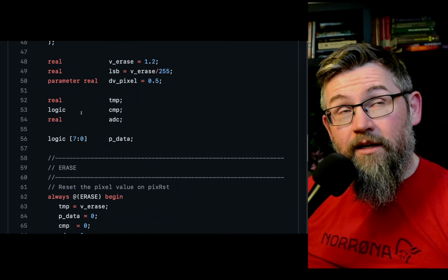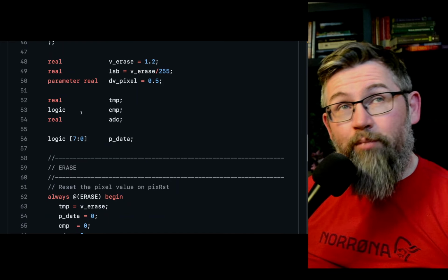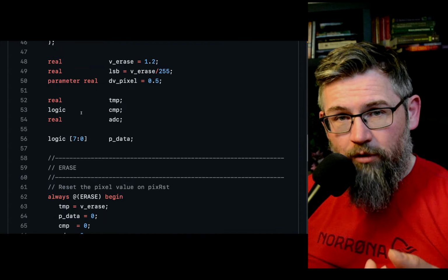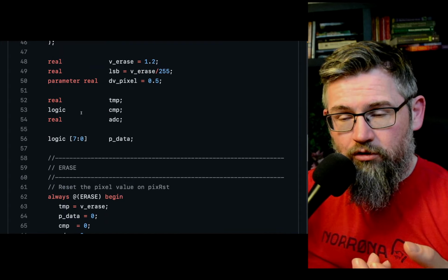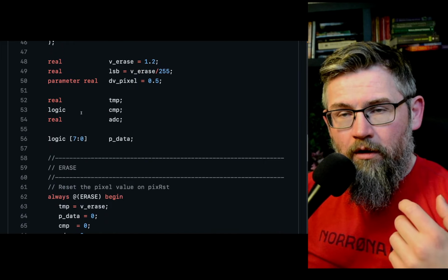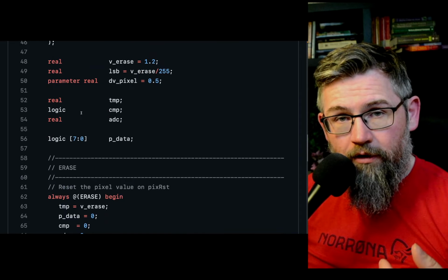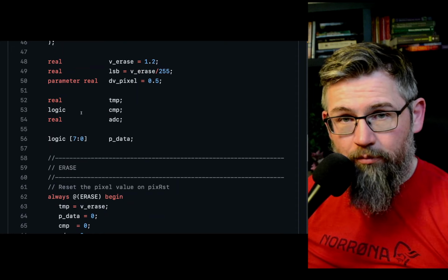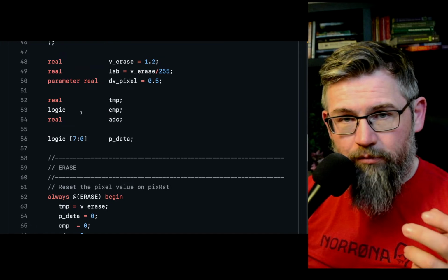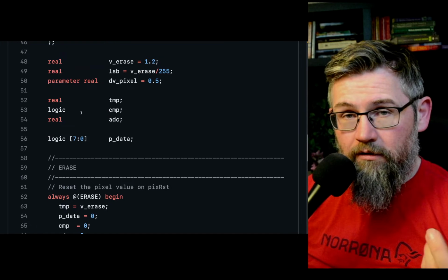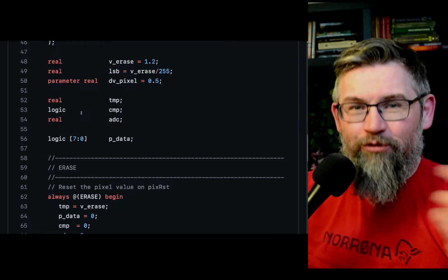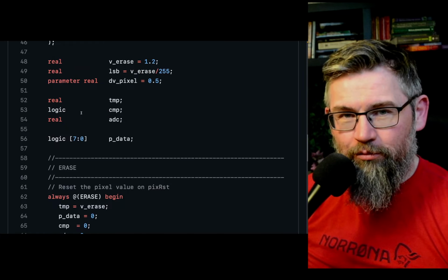So it's not a perfect way of doing it, because you have a SPICE model of your system and an analog Verilog model of your system, and you have to ensure that those two are similar in behavior. But the extra complexity is worth it because you're able to simulate the top level of a chip in an efficient manner. And, for example, if you have communication between two chips, in the digital simulation you can instantiate two versions of your chip and get them to talk to each other, which would not be possible in analog simulation.